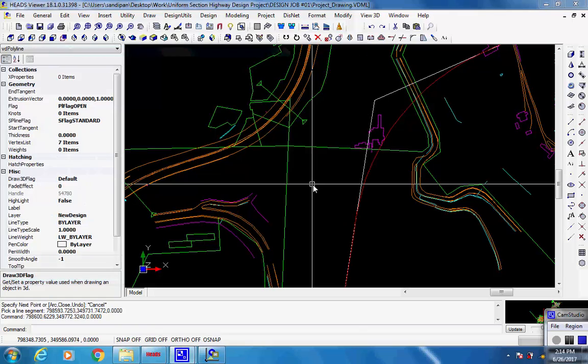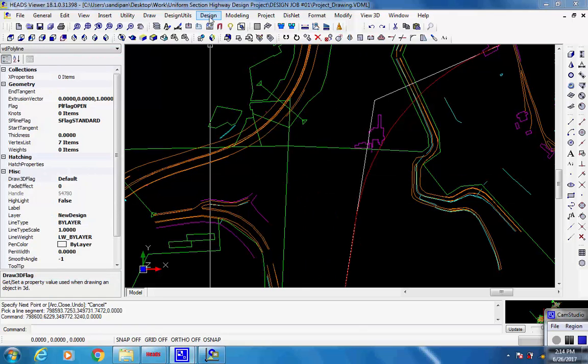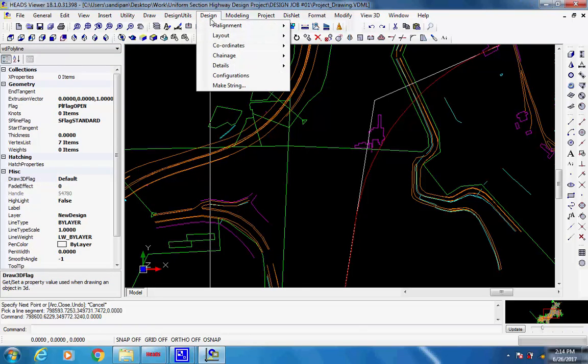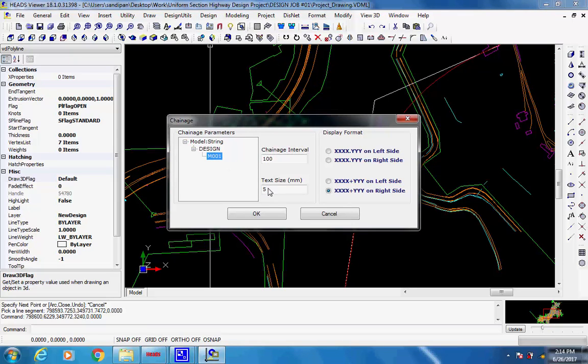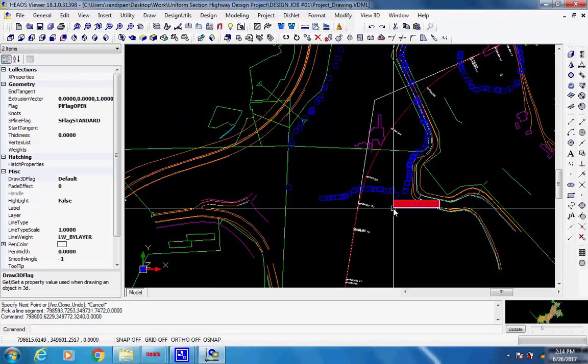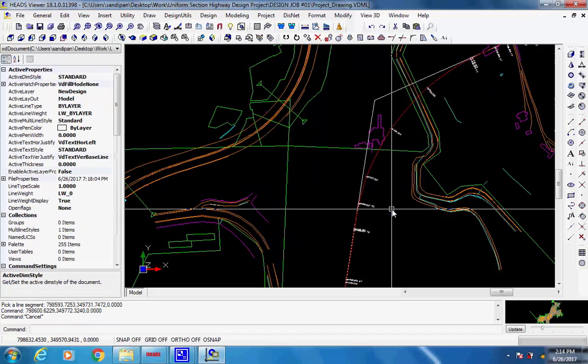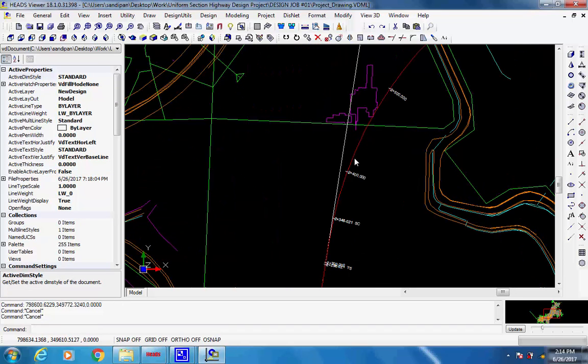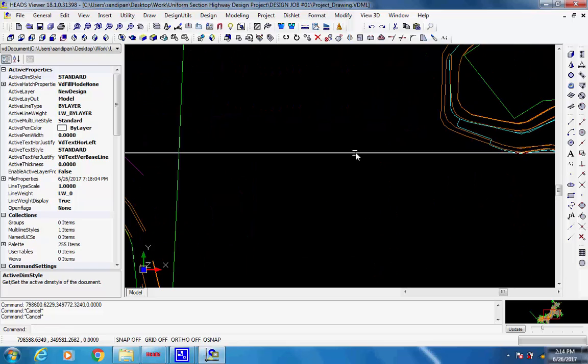We already turned off the layers C001, C005 and ELEV for contours. We display the chainage stations and curve details at various HIPs and view the design. The report file alignment.rep contains various details related to the design of horizontal alignment of the road center line created as string M001 under model design.